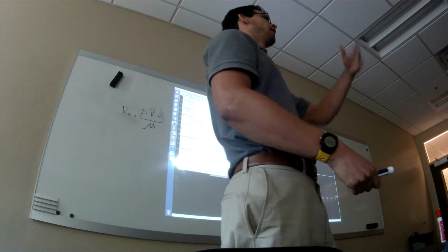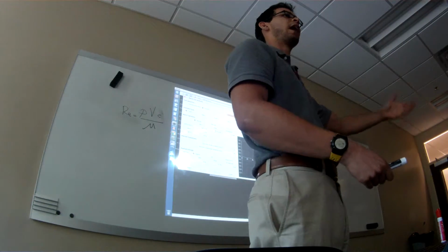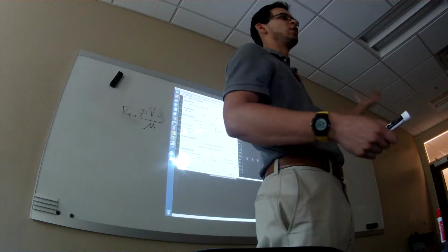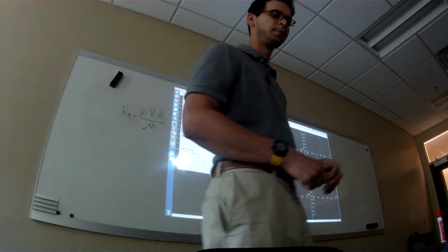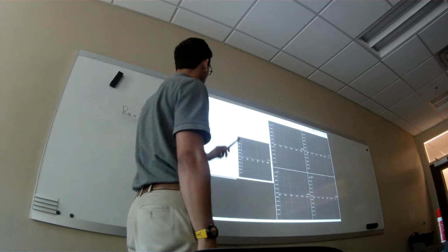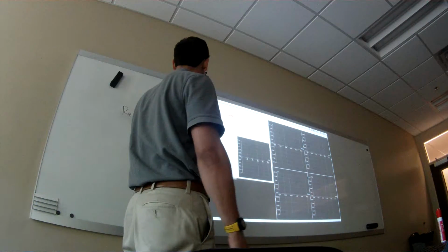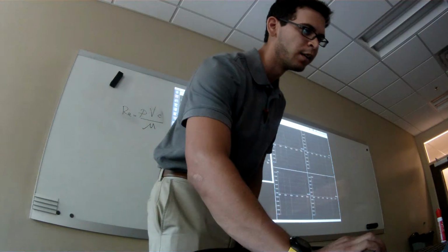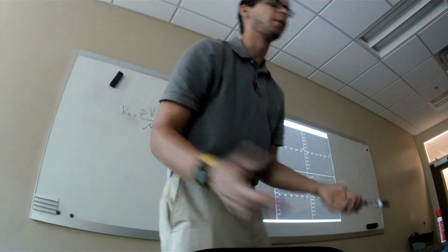And then you've got hyperspeed aerodynamics or hypersonic aerodynamics where the Reynolds number is huge. It's in the millions and tens of millions. I'm going to run a really simple one from 100,000 to 200,000 in increments of 10,000. I'm going to set my Mach number to 0.1. I'm assuming I'm not flying very fast.